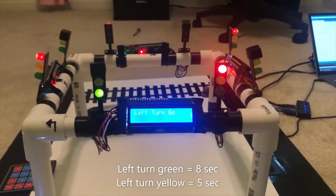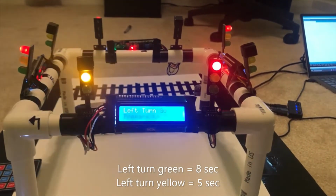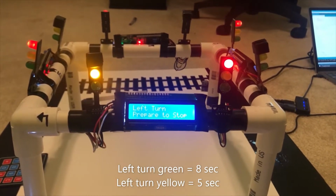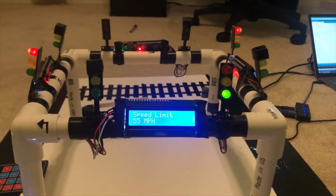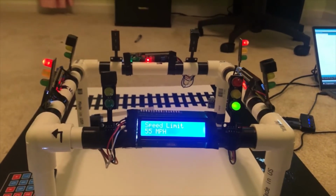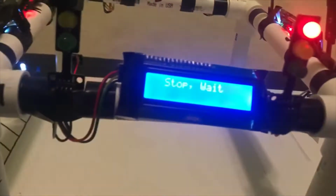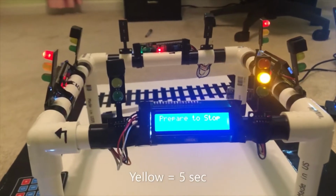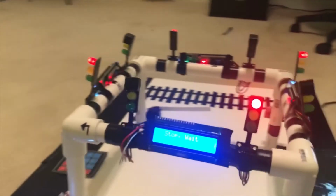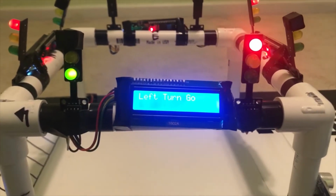The traffic light system begins with north and south green turn signals saying left turn go, left turn prepare to stop, and then the lights will go green for 15 seconds with a speed limit of 55 miles per hour. Anytime the other directions are red, the LCD is going to say stop, wait. All directions will be red for 2 seconds, and then east and west will begin with the green turn signal.